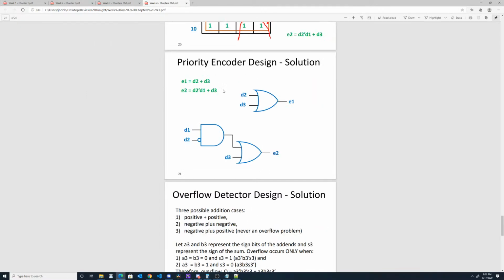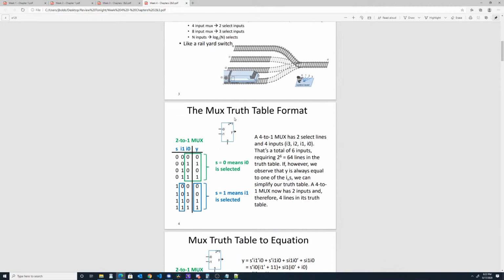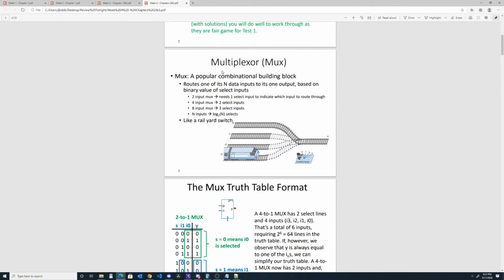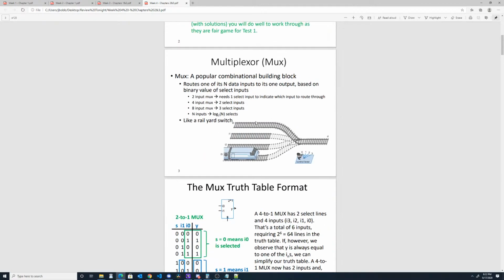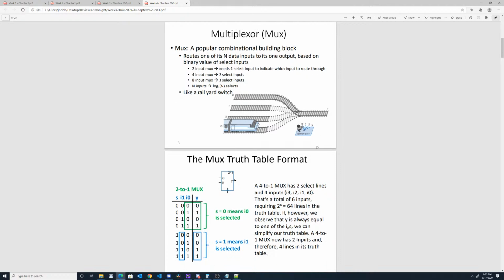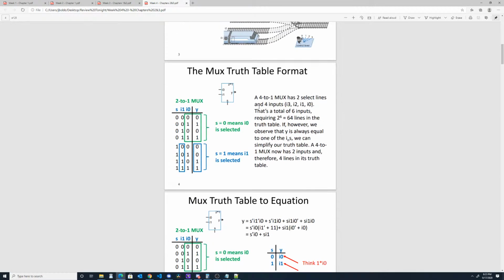All right, I'm going to just go through real quick. So we have multiplexers, right? The multiplexer is kind of like a big switchboard. So we have some kind of selector here. Those are the selectors at the bottom of the mux, and then we have our individual lanes we can take. Each of these lanes corresponds to a certain position on this control lever. So typically you see muxes drawn like a box like this with selectors.